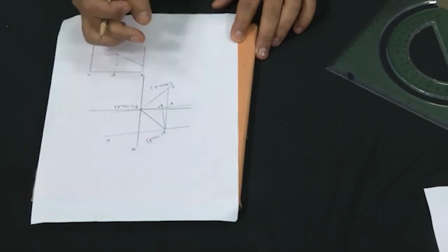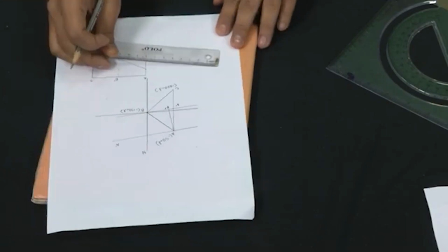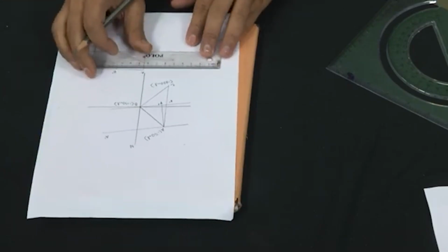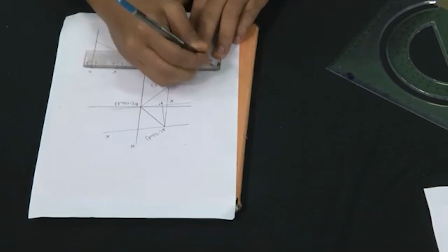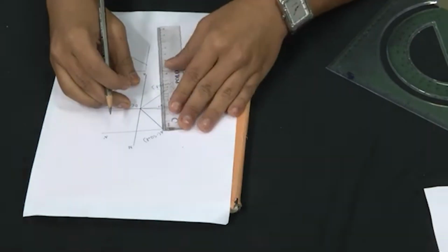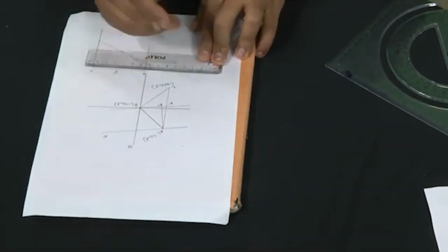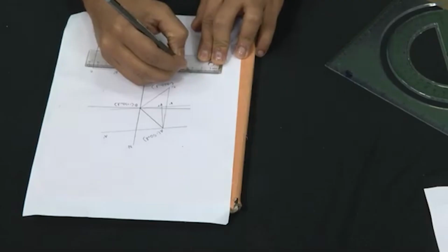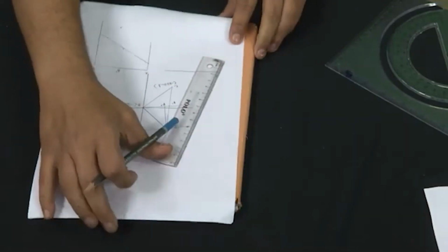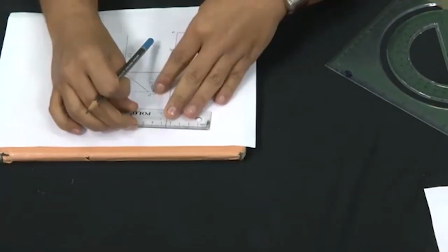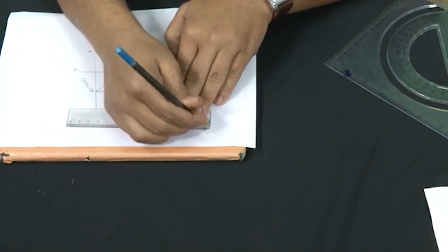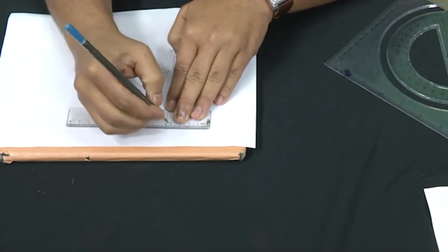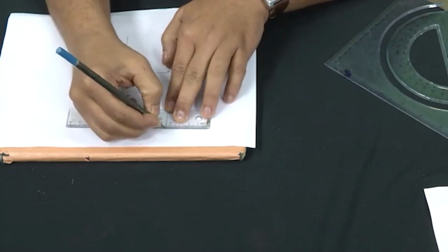in the plan. In order to find out the dip, we will first construct another subsidiary diagram in which along the x axis we will plot the distance of A P dash, and now we know the vertical spacing between the A P dash, which is basically 80 meters. So, I go to the 80 meters according to the scale.